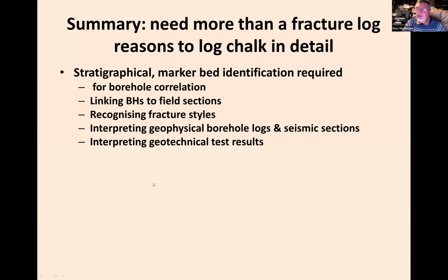And the reasons to log the chalk in detail include these sorts of things: borehole correlation, boreholes linking to field sections. And a very simple thing, if you don't know where you are in the chalk, you can't go out and sample the quarries and cliffs to check what the properties of those particular units of chalk are. Recognizing fracture styles, or beginning to predict perhaps what the fracture styles are likely to be. Interpreting geophysical logs and seismic sections, vital, absolutely vital. And interpreting geotechnical test results.